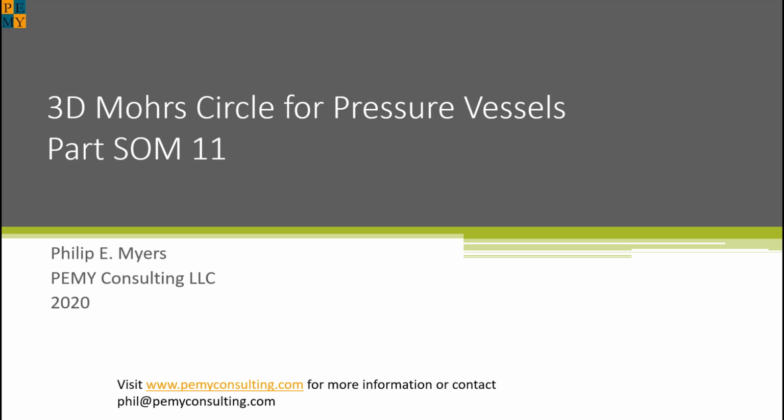Earlier in the series, we reviewed the basic principles of the Mohr Circle, which provides insight about how stresses behave at a point in a material subjected to an internal stress state. Since failure of ductile materials like steel often occurs by shearing stress failures, it's important to understand how shear stress and maximum normal stresses, or principal stresses, relate to each other. Because a 2D Mohr circle only captures the stress state strictly within the plane of consideration, or in the XY plane, we will find that the absolute maximum shearing stress is not always given by the 2D Mohr circle.